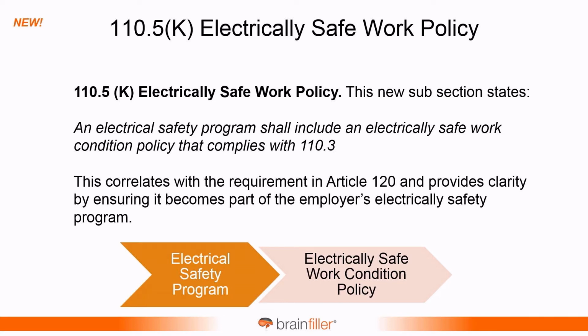Another new addition, the electrically safe work policy. It's a new subsection, and it just states that an electrical safety program shall include an electrically safe work condition policy that complies with 110.3. Now, this may seem maybe obvious, but now it's part of NFPA 70E, that if you develop an electrical safety program, it has to have in there the electrically safe work condition policy. So this is a requirement. Now, again, emphasizing the electrically safe work condition.